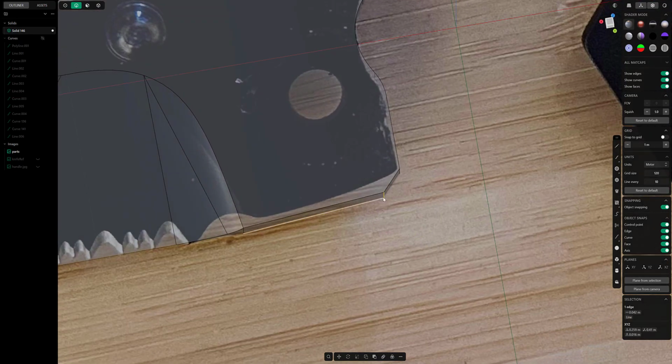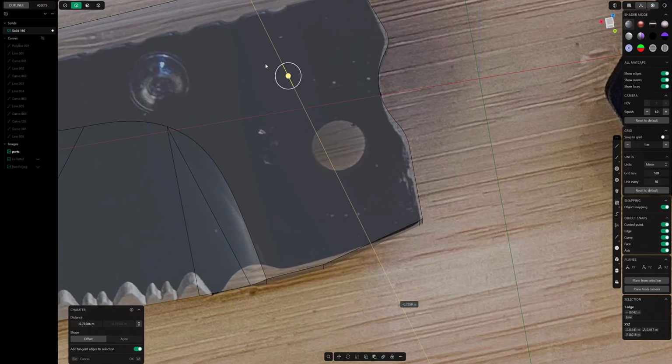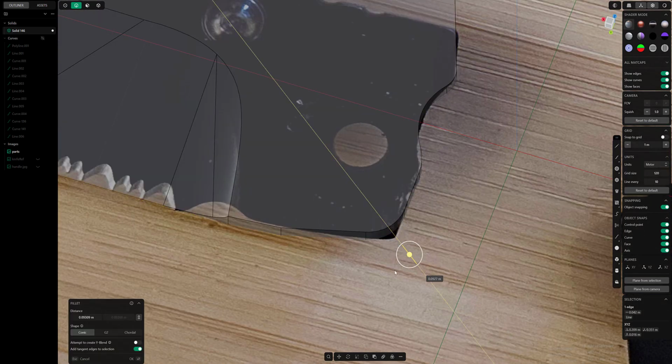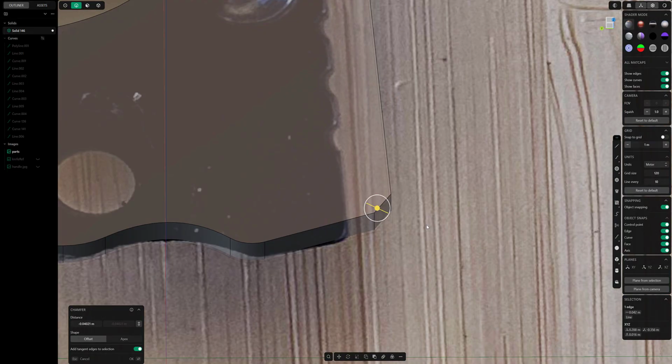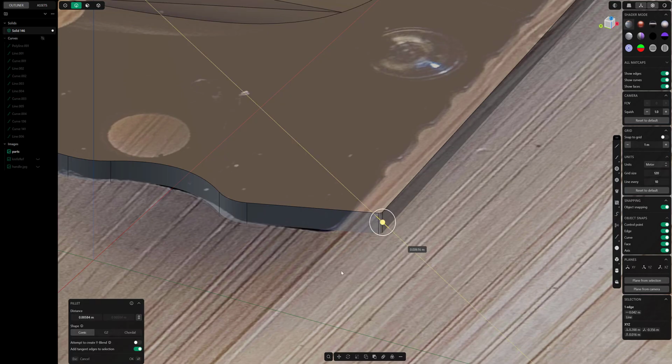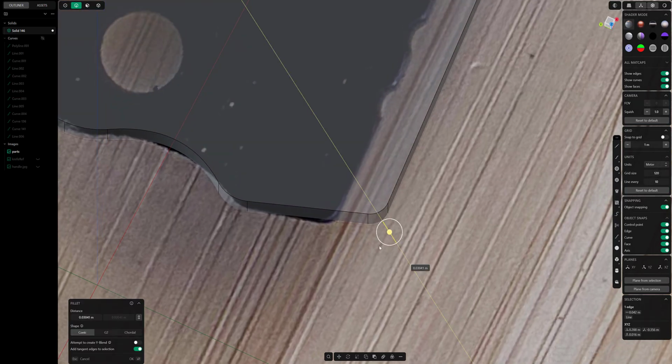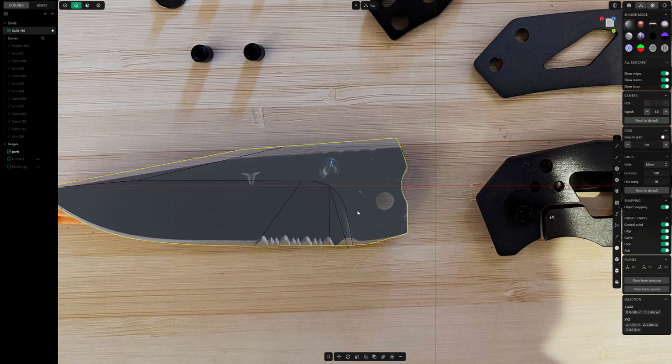But here, instead of bringing in another edge and cutting it, I just chamfer until it kind of disappears through the other end or the bounding box, and then do another chamfer just to get the angle of that bottom edge that I want.